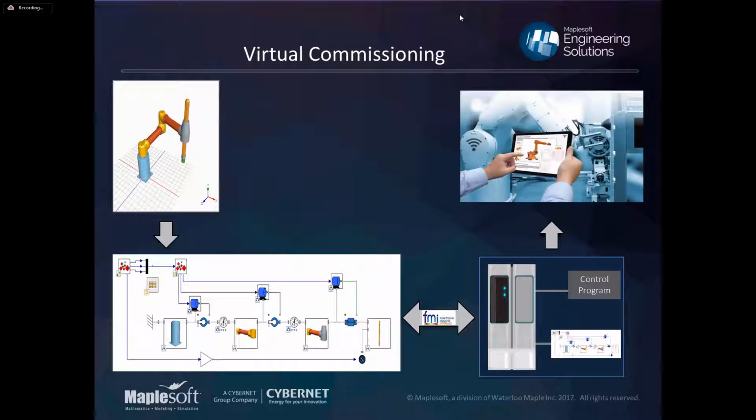Going from there, these digital twins, these models, they continue to have value a bit further down the line when things are actually in production. So we're getting a little bit outside of the scope of virtual commissioning, but having a sort of gold standard of how your machine ought to perform means you can run that thing in parallel the whole time. And as soon as your machine starts to drift from its ideal performance, you're going to notice that far sooner than just what your own ability to gauge performance of that machine looks like. So it's a great tool for maintenance diagnostics.